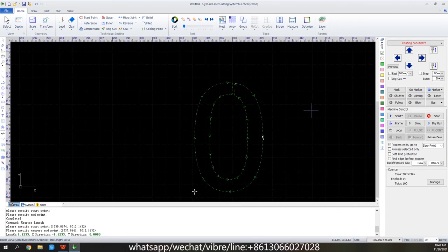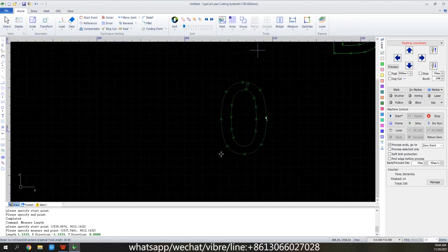Now let's come to the last feature. If we don't want parts to get automatically optimized when input, click Manually Optimize. In the drop-down menu, we have this break grade, which is used to cut up the inner waste so as to avoid it going up and getting in the way of the cutting head.